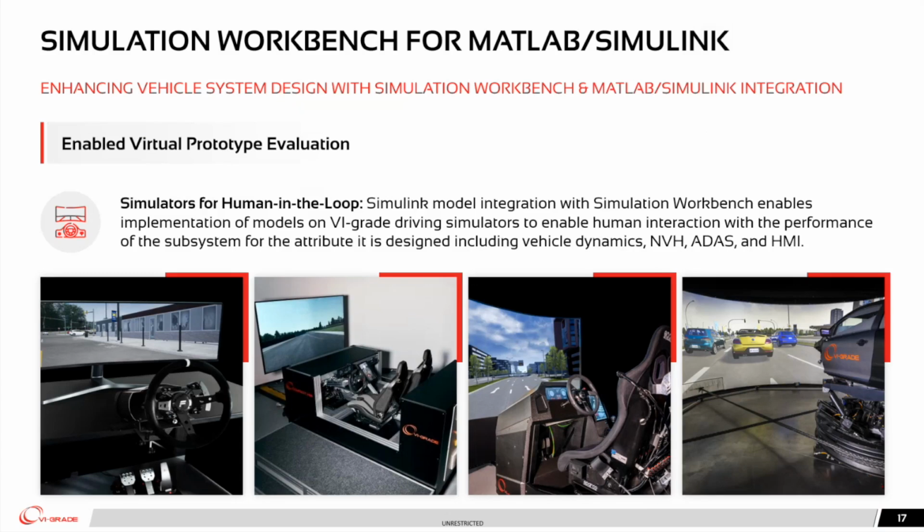That broader environment can include human in the loop, which is basically what our driving simulators do. So you can take the Simulink model and do integration with software called Simulation Workbench that runs in our real-time environment and has access to a real-time database where data is exposed to subsystems at that level.